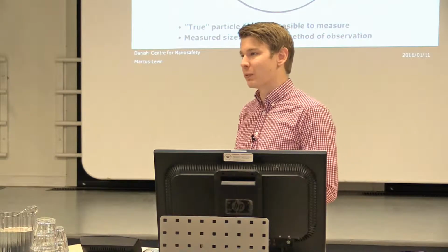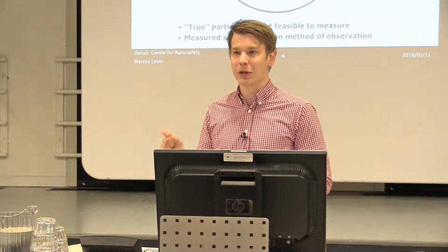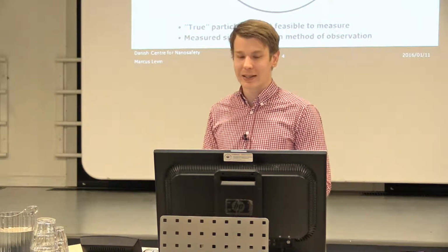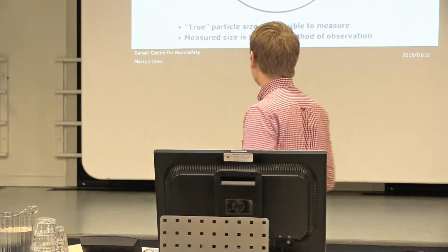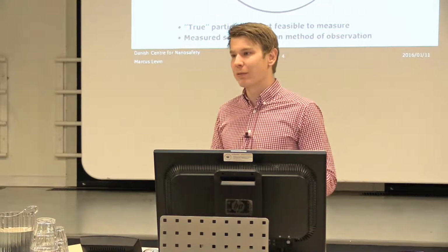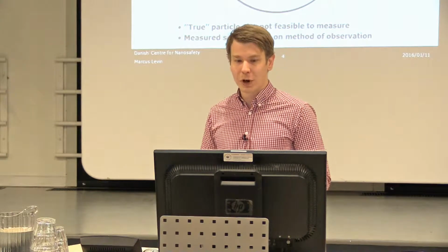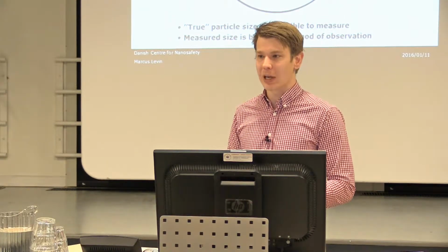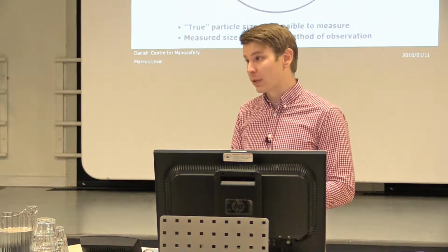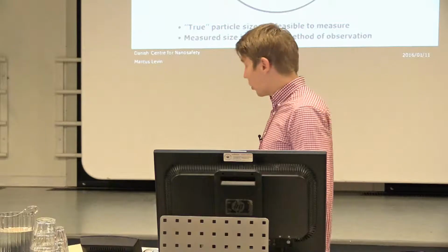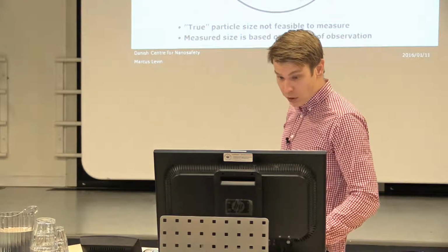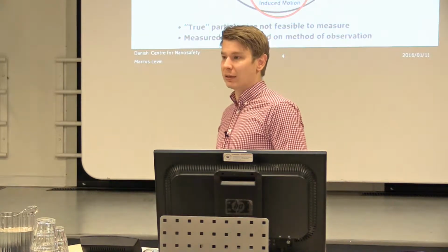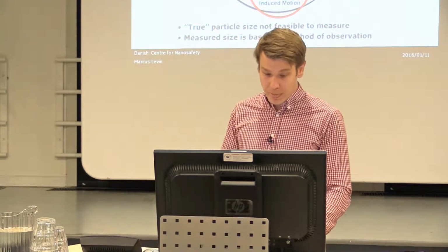And if we want to measure size, we can do this in a lot of ways, because it will never be feasible to look at every little single particle that we inhale and determine the exact size of it. So instead of knowing the exact size, we have to study some parameter or observe some parameter of the particle, which we can then link with some type of size of the particles. For example, we can look at how the particles scatter light, or how they behave due to gravity. Or, as I've been focusing in my work, how particles behave in electrical fields.